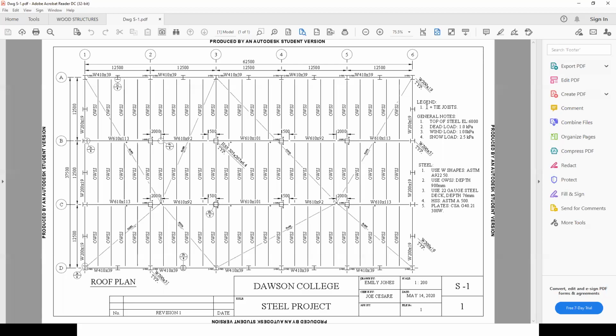They put one for a tie joist, and then they used the same symbol for the knee brace. I would suggest that you come up with another symbol for the knee brace. Because when we design these things, we say we're going to laterally brace them, and therefore you should use a different symbol. So in your legend, here they put a plus sign for the tie joist, so the manufacturer will realize, and we'll talk about why we need tie joists when we talk about columns.